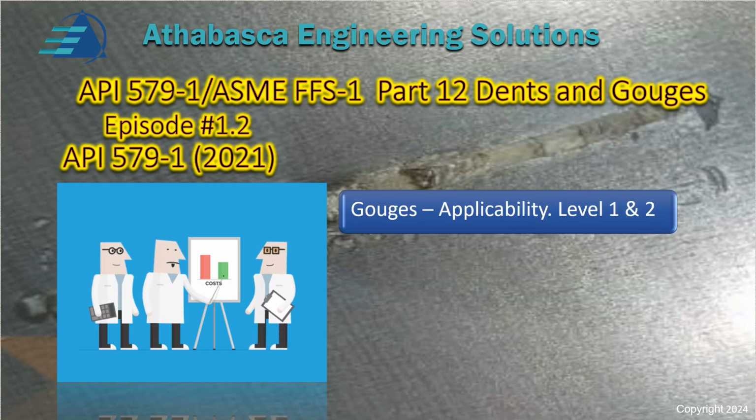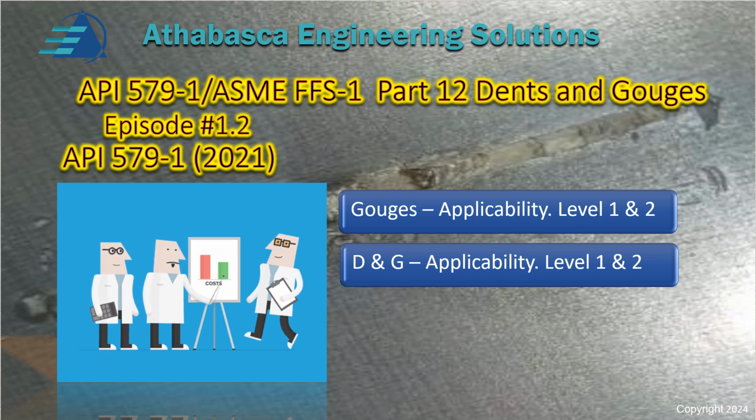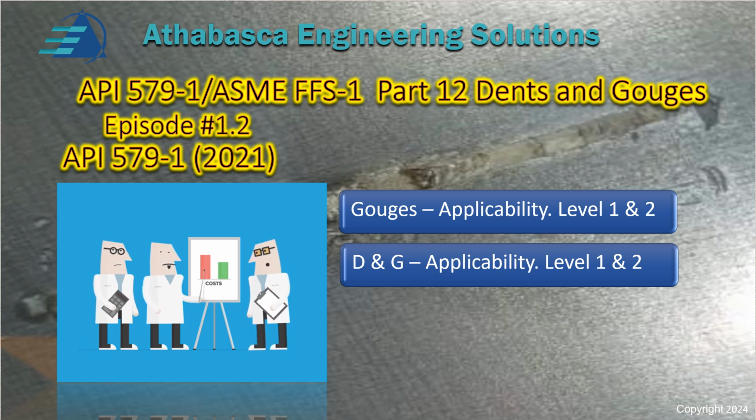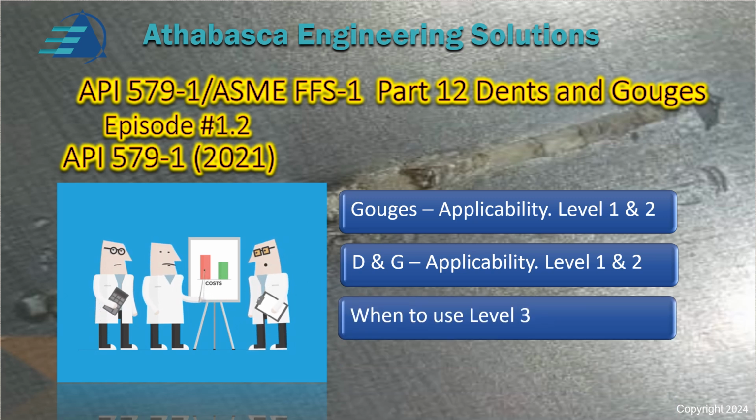So gouges applicability will be the first thing that we'll look at, level 1 and 2. The previous video, we already looked at level 1 and 2 dents. Secondly, we're going to look at the dent and gouge combinations and the level 1 and 2 assessments. Recall, level 1 is a very basic one. It's designed for 10 or 15 minutes to look at it on paper. Level 2 is at least half a day's work, depending on the complexity, of course. And then when to use level 3, which requires an expert to look at, and there's some advice on that.